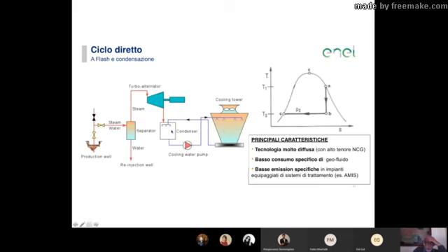So what is usually done at the condenser is that you have a pump called an extractor, represented here, but actually you have an extractor that is just for gas. On top of the condenser, you're extracting the gases to be able to maintain a very low pressure in the condenser.